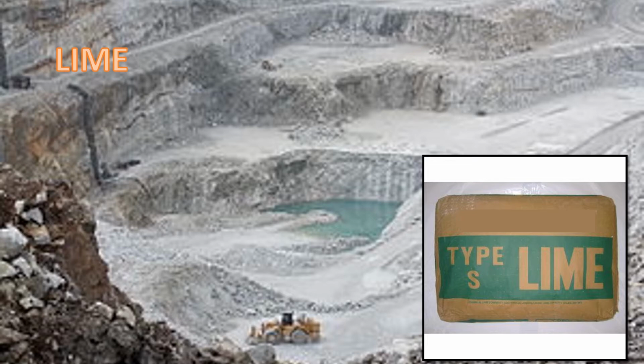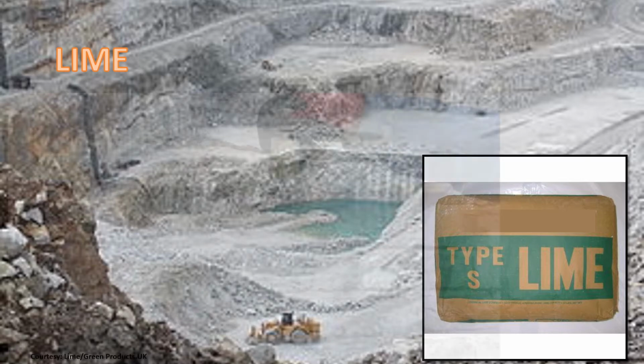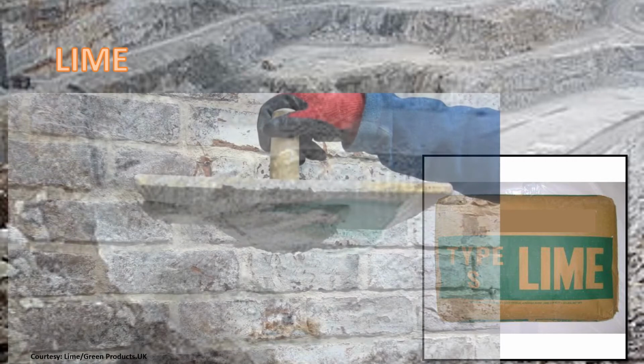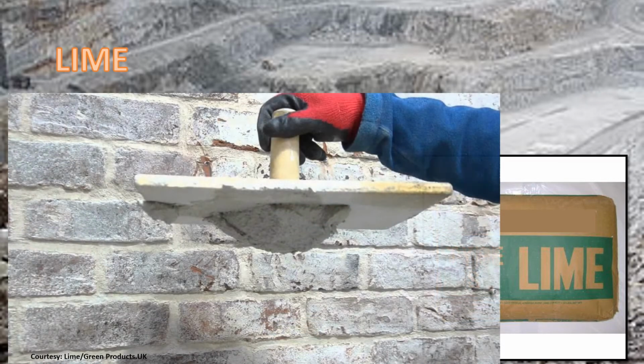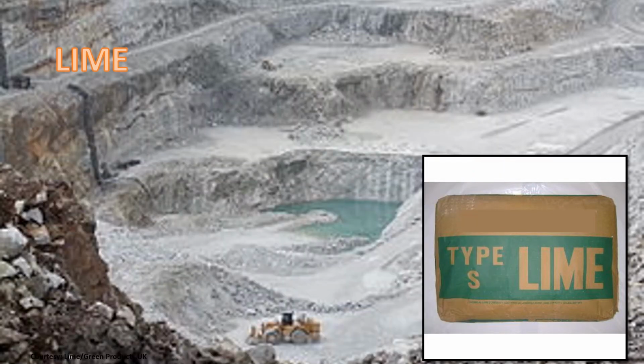Lime is used to make common cement more workable. Lime also has additional complex qualities. Lime adds cohesion to plaster. This makes plaster stick better. In the US, we have Type N, or normal lime, and Type S, we call special lime. Type S lime is a hydrated lime and made for plastering.